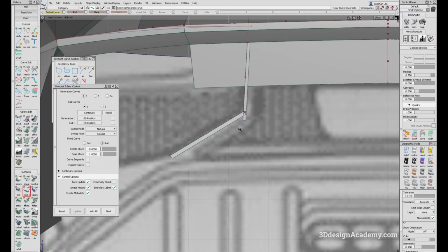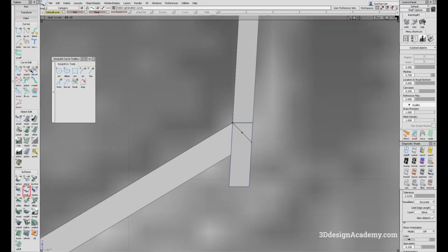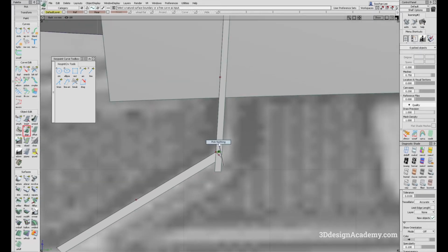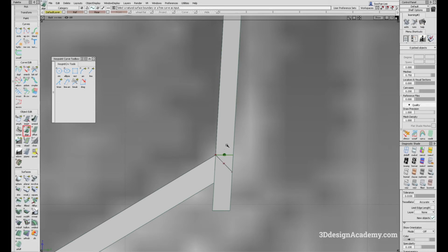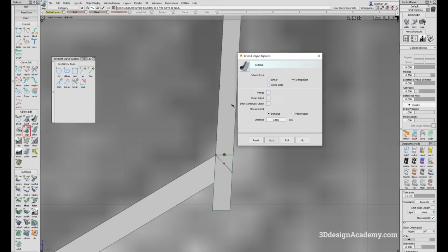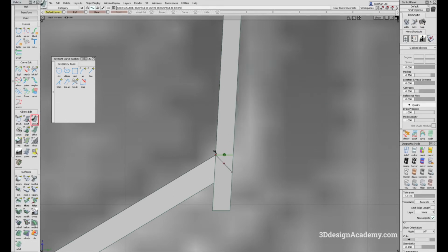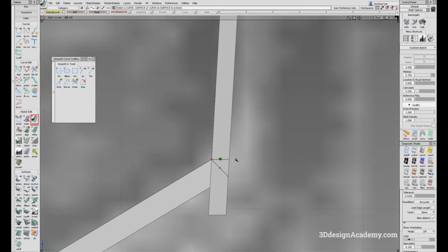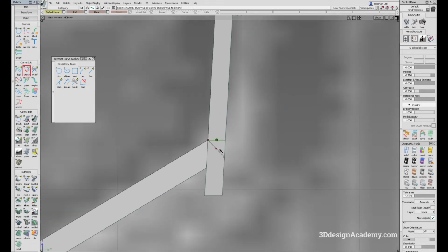Okay, so I want to make sure that they are about similar in thickness. And the reason why I'm extending this curve is so that when I'm going to just do an edge align like this, whenever I make changes to this, basically if I extend this surface with the history with merge on, then it's going to delete the surface, delete the construction history, and I cannot make any adjustments.